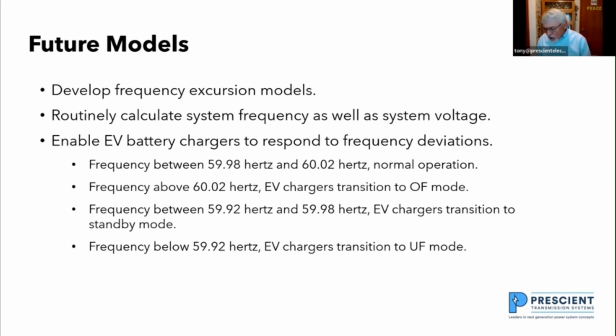They're not using electric vehicle battery chargers, I should say. They've actually got a large battery installed there. And if they lose generation, the battery will work for 10 minutes until they can bring up some quick start generation and recover the grid. And what that does is it reduces the spinning reserve costs on the power grid.